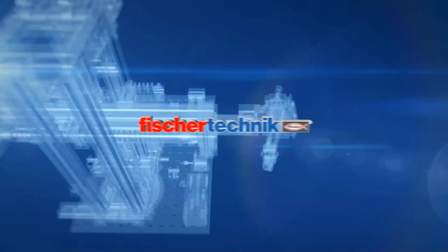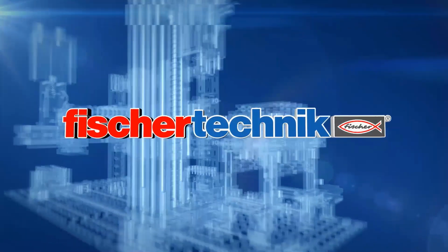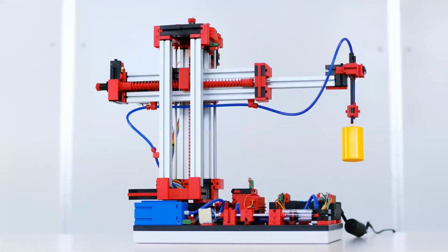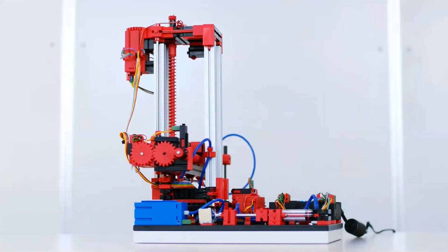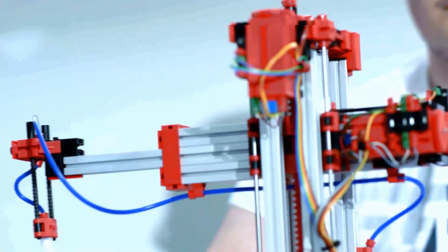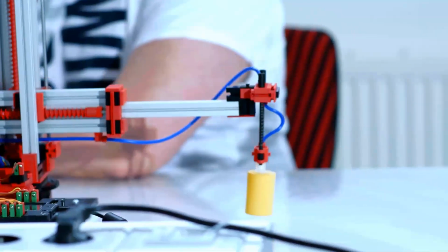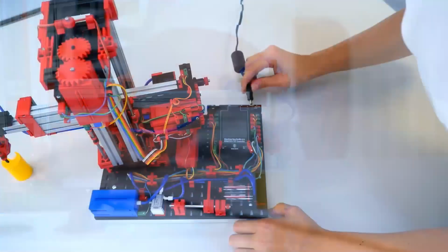Now, as you're going to see in this presentation, the vacuum gripper is a 3-axis robotic model with a vacuum gripping device. The model is designed to precisely pick up and position workpieces in 3-dimensional space. The model includes 3 encoder motors, 3 push-button limit switches, a vacuum suction device, a compressor, which is the blue brick component that you'll see in the video, and a solenoid valve.